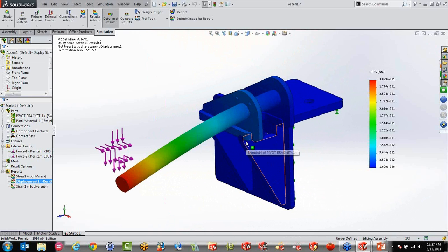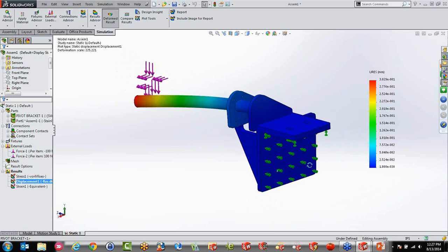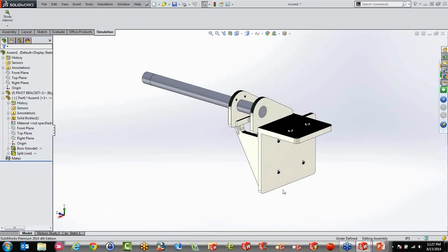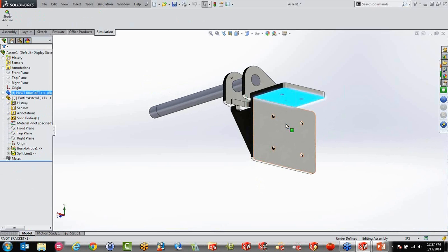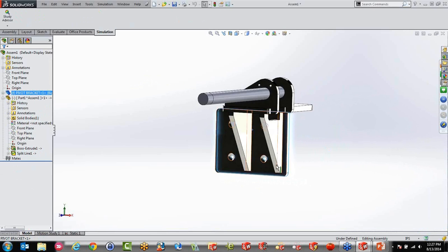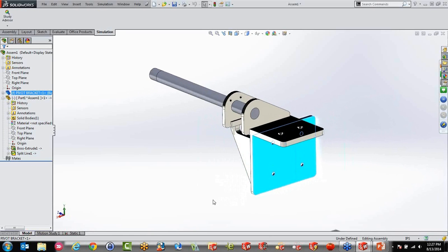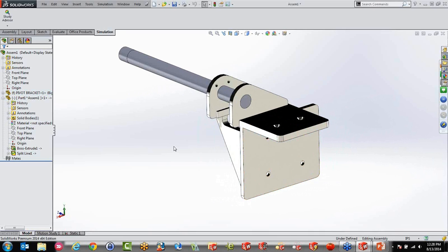Also, another thing I just quickly wanted to show as we're talking here is that what you've seen me do so far is I've taken an approach in the beginning where I was like, all right, just give me some feedback, and then I have really just narrowed it down, making the mesh finer or working with it in that regard. SolidWorks has a lot of neat tools in here we can work with. For example, to this point I have only fixed these two areas, but in the real world you can see that I actually have some bolt connections in here. So this one is actually bolted to something else. Maybe I want to see how that is affecting my whole scenario.